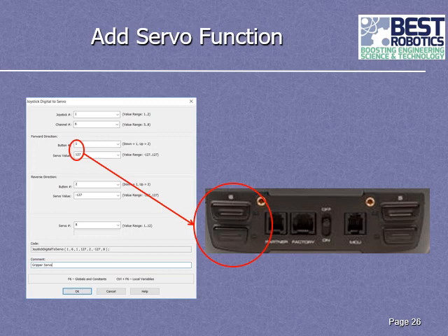So a servo has a center position when it's at rest at the 0 mark, and then you can go plus 127 or minus 127. In this case, we're going to go plus 127, which says go as far to the right, or open, as you can go. Now, once you put this into place and you decide, I don't know if this is exactly how far I want this thing to open, you can come back in here and play with this number until you get it to move exactly how much you want.